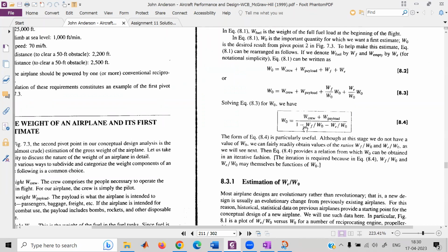So there is aerodynamic optimization involved here for fuel optimization, right? You want to have minimum CD naught, and the same goes for structural. You want to keep the weight minimum, so you choose materials, shapes and sizes of the objects required for the aircraft design very optimally, right? So you require less and less weight. So that's how you minimize the overall aircraft weight.